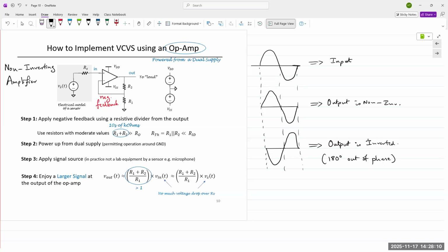In noise cancellation technology, a microphone captures the ambient sound, inverts it, meaning it's 180 degrees out of phase, and adds it to the original input, and the resulting output is 0. That is the fundamental operating principle of noise cancellation. That's where inverting comes in.